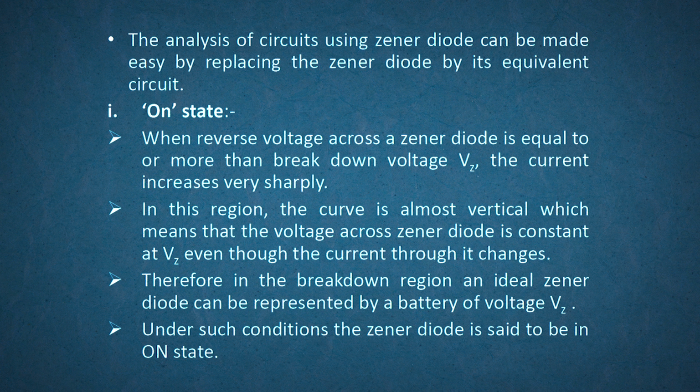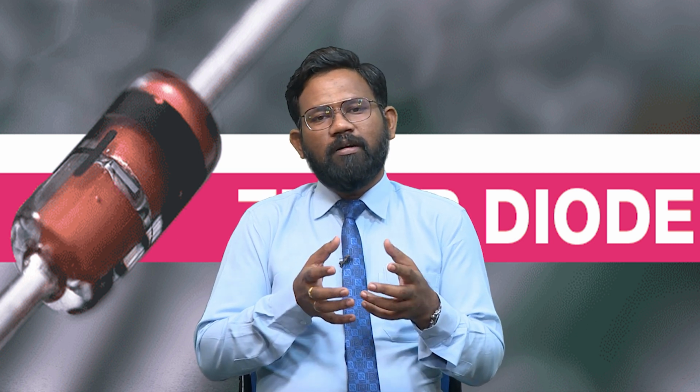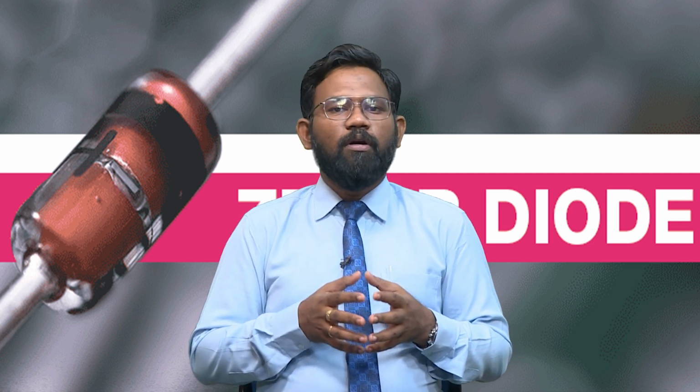Therefore, in the breakdown region, an ideal Zener diode can be represented by a battery of voltage Vz. Under such conditions, the Zener diode is said to be in on state. So, in on state, the Zener diode is simply denoted by a battery, or a voltage source whose voltage is Vz.